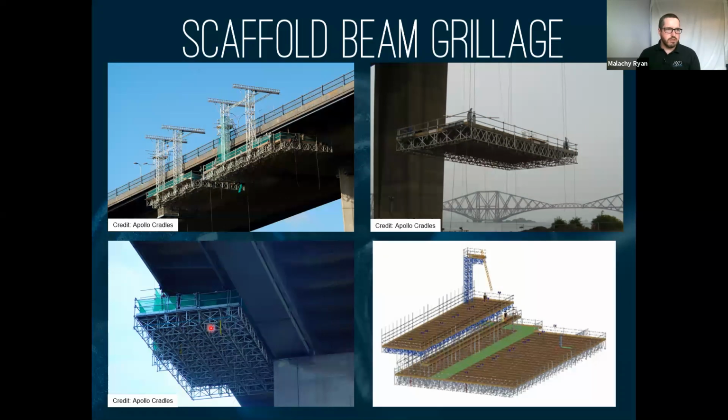Bottom left-hand corner here, I think, is the Fort Road Bridge again. The reason I put up this image here is you can see a scaffold gate in this end of it here, which is a bit unusual to see it randomly with nothing on the other side of it. But this platform is left stationary in its position, and the permanent gantry that ran on these tracks for the bridge maintenance was used to travel up and down, and they could walk between them for getting operatives to the work face.